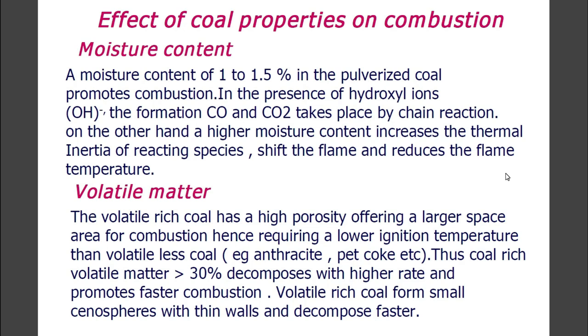Thus, coal rich in volatile matter, greater than 30%, decomposes at a higher rate and promotes faster combustion. Volatile rich coal forms cenospheres with thin walls and decomposes faster.